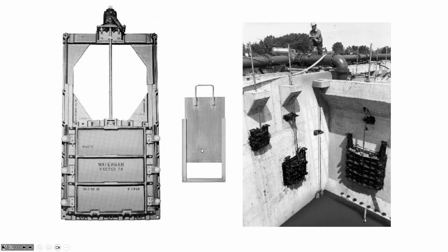There can be a lot of these gates that feed into flow equalization basins in water treatment plants, where when you've got sanitary sewage coming into a treatment plant, the biological systems that are used to break down pollutants operate at a pretty constant rate. Bacteria can't be turned on and turned up dynamically in the same way that you can turn up a mechanical pump.